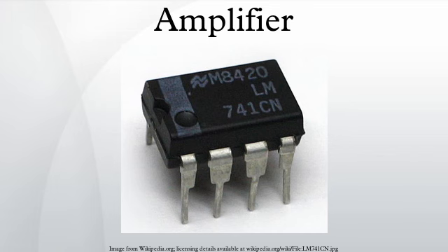In the case of high-powered audio applications requiring long cables to the load, for example cinemas and shopping centers, instead of using heavy-gauge cables it may be more efficient to connect to the load at line output voltage with matching transformers at source and loads. To prevent instability and/or overheating, care is needed to ensure solid-state amplifiers are adequately loaded. Most have a rated minimum load impedance.